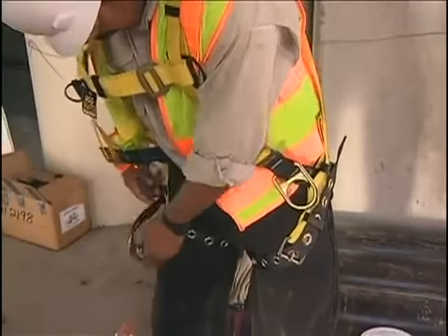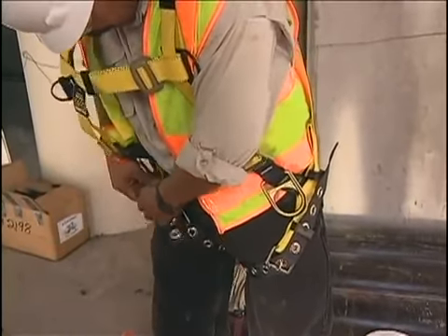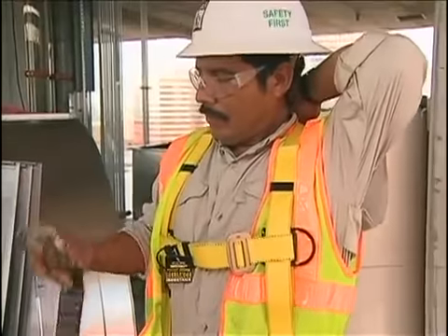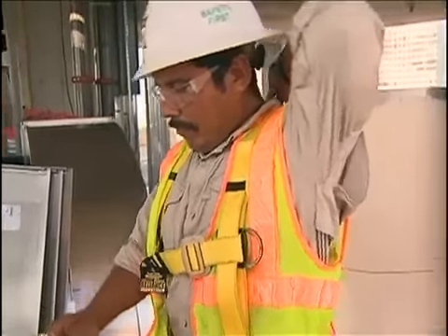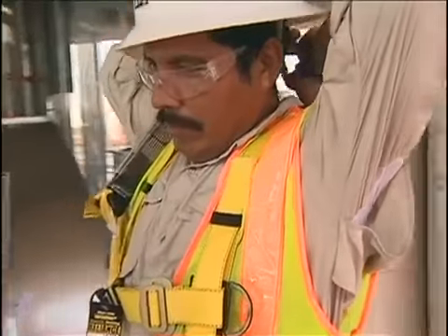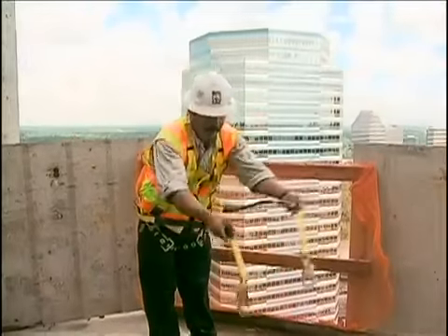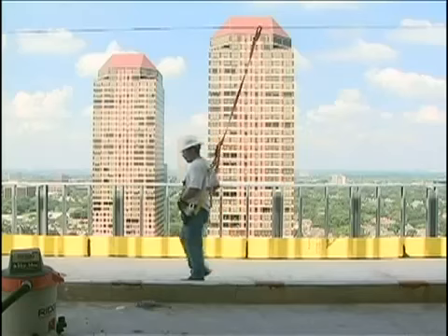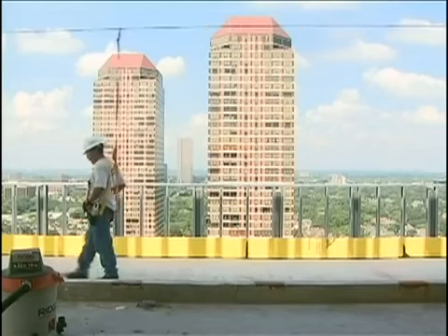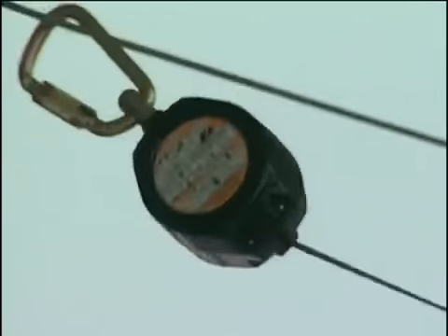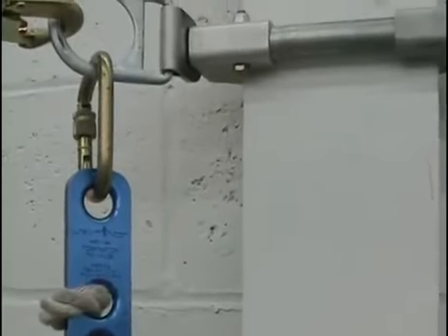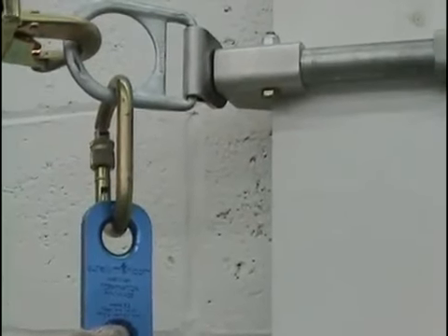If worn correctly, a personal fall arrest system can save a worker's life. If worn incorrectly, it can cause additional harm to the worker, possibly causing grave injury. A personal fall arrest system consists of a full body harness designed specifically according to the workplace application, a shock-absorbing lanyard or self-retracting lifeline designed to take the strain out of a fall, and an anchorage, a secure point of attachment for lifelines, lanyards, or deceleration devices.